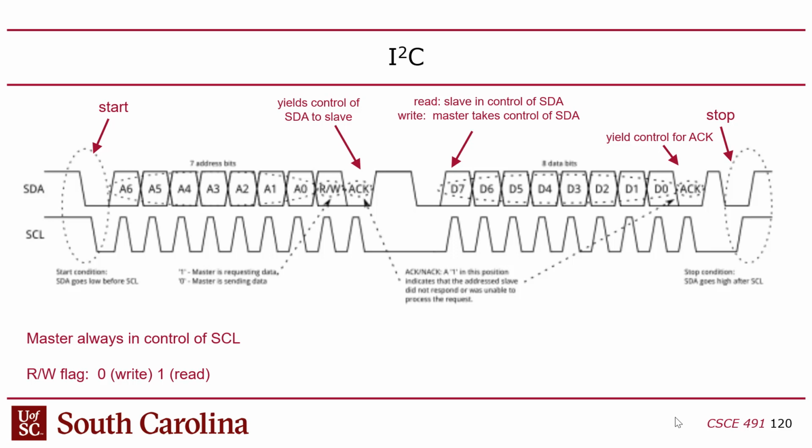Yeah. Make sense? So they're not really bits, they're just signals, or events, or situations. I don't know what you call them, start and stop. And then the bits are sent using a latch mechanism, where the data bits aren't sampled on the edge of the clock, they're sampled whenever the clock is high. So the data doesn't change when the clock is high, and the clock being high means I'm going to let the bit in. So it uses a latch. It's very rare to see latch-based systems, level-sensitive clocks, but I2C is an example of that.